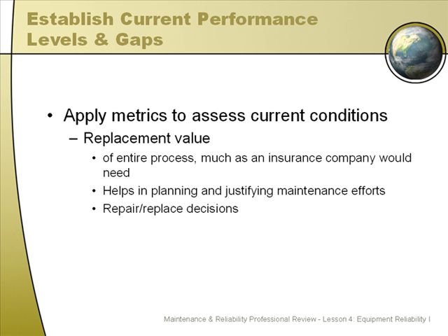If you have a high value piece of equipment or a high value process, spending some money to maintain it will be easy to justify. Replacement value also gives you a nice window into the repair or replace portion of your decision making. If you have a piece of equipment that has absolutely no replacement value and it's fairly easy to maintain and it produces well, it might make sense not to replace it if it's doing the job.